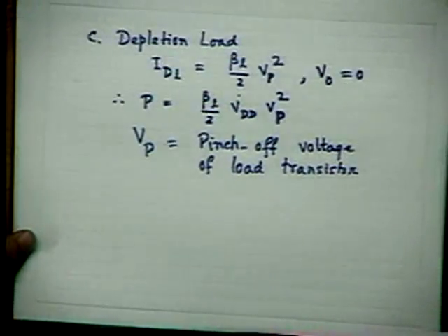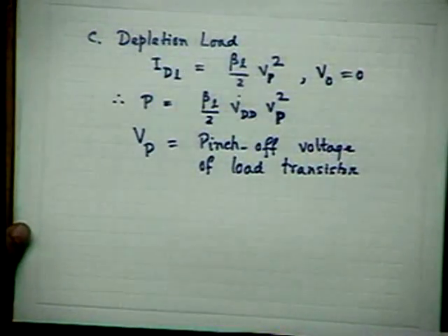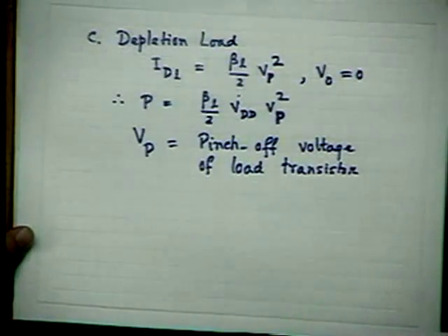So this is in short the power. Now, how you can get simply the expressions for power dissipation in MOS inverters, and how you can have some kind of optimization of these power dissipations in the various inverters. Our conclusion at the end is that CMOS is definitely the best, much better, very, very good compared to any other form of inverters, so far as power dissipation is concerned. But what is the drawback of CMOS?